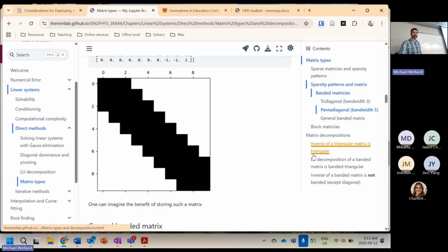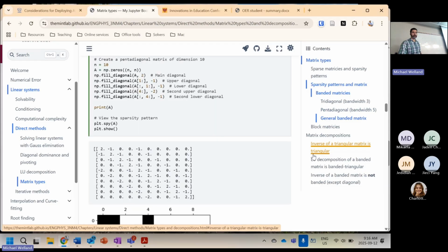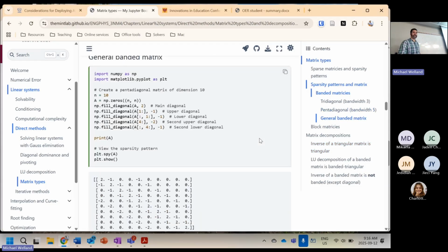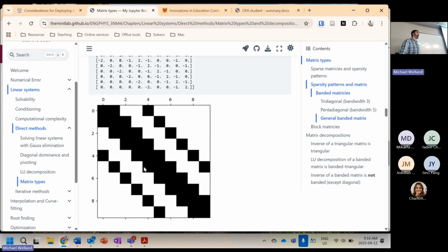And you can also have generalized cases, right? These are all banded matrices because they have these nice ordered arrangements. This is actually very common in finite difference. Finite element, not so much, because of the way the triangles fit together when you're tessellating all this stuff. Finite difference, or if you were doing that on a rectangular grid, then you would also see this sort of structure.